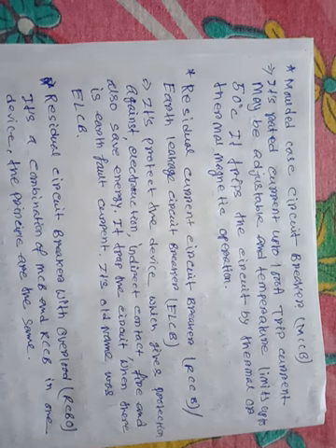The trip current may be adjusted, and the temperature limit is up to 50 degrees Celsius. It trips the circuit by thermal or thermal magnetic operation. They are used in different types of industry and commercial purposes. Sorry, it is not used for residential purposes. It is used for industry or commercial plants. In residential use the current is less, and where the current is high, the molded case circuit breaker is used.